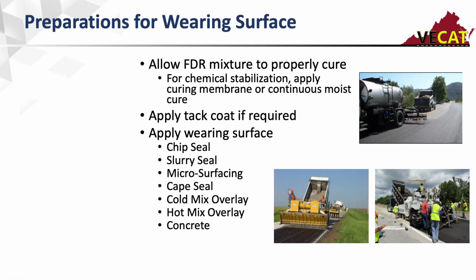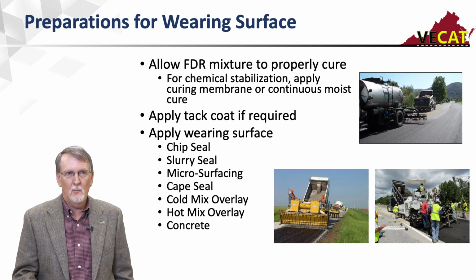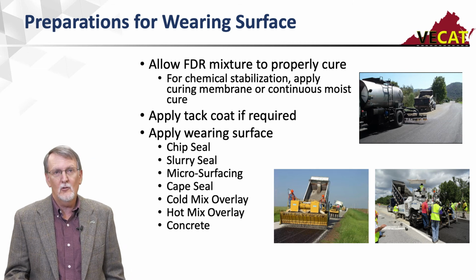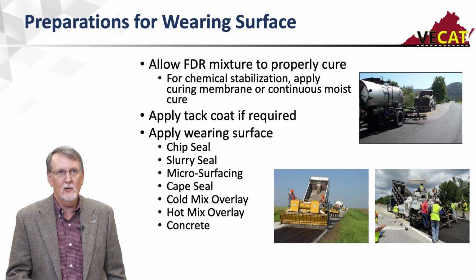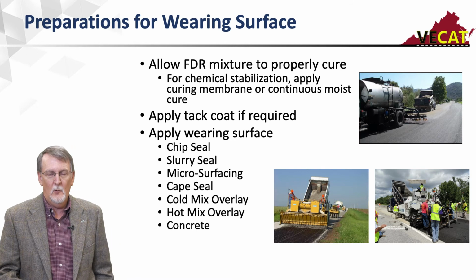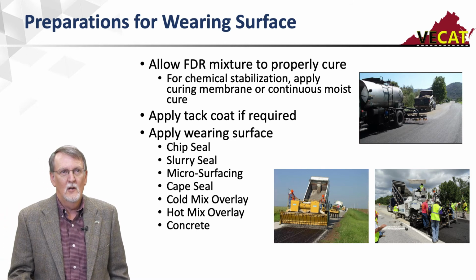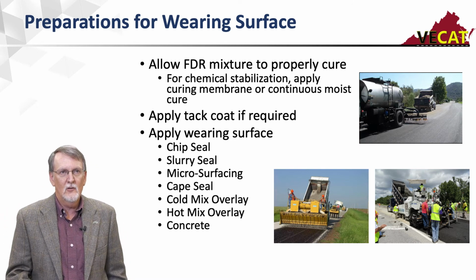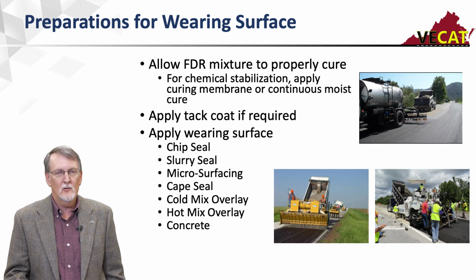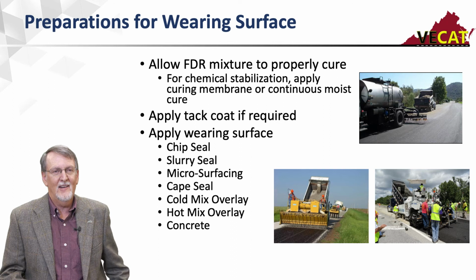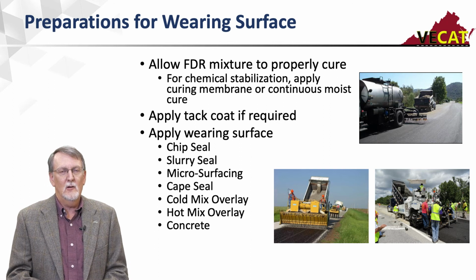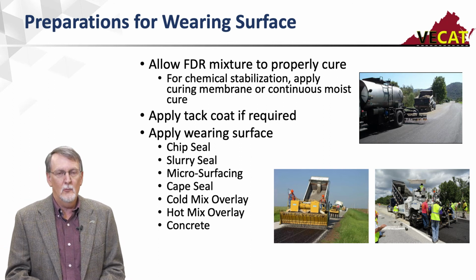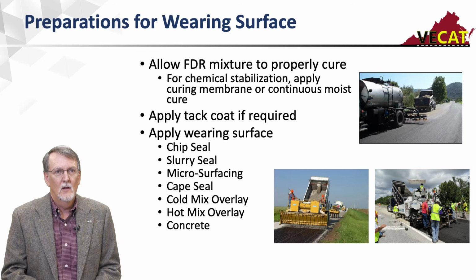As far as preparations for the wearing surface, this mix needs to cure out. So for chemical stabilization, I want to moist cure it continually until I can get a curing membrane on it. And we want to leave that curing membrane on it for several days until it's gained its strength before I put the final wearing surface on it. With the chemical one too, I also want to be careful to not let heavy loads go down on there because I can break this material up before it's gained adequate strength.